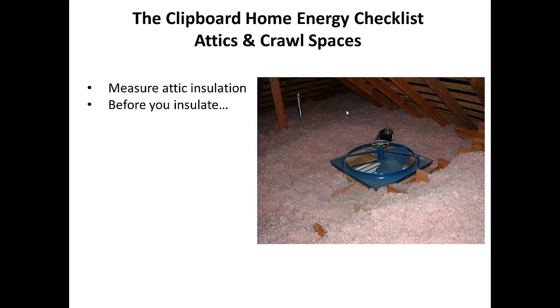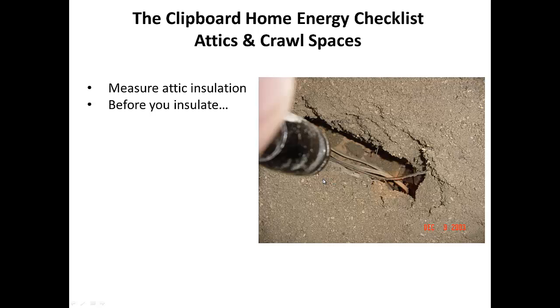Now here's an attic fan that's up there, and we'll see an example of it later on, but you probably want to take some styrofoam or some lumber or something and make a dam around the perimeter of this attic fan, so that when they put in their insulation, it doesn't fall down into the attic fan. It can go right up against the side of it.